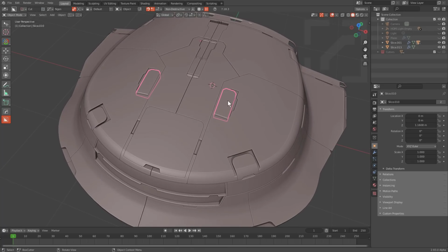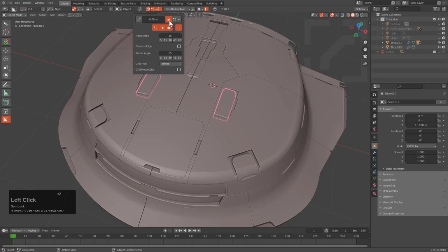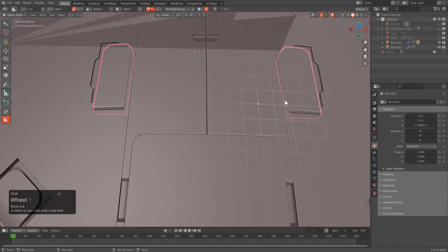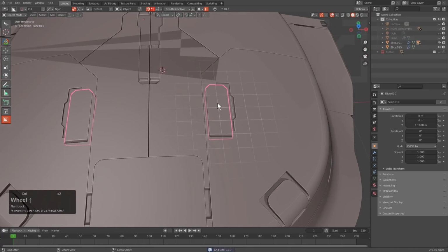Traditionally in Boxcutter, we had a grid where whenever you hold control, you're able to roll the wheel to make the grid larger and smaller on the fly as needed. However, when it came to extending its functionality, we also added a few additional options to make people's lives easier. For example, right now, in order to keep this grid up, I have to hold control, and the moment I release control, the grid is gone. However, I could activate this lock icon where if I tap control, the grid will remain up on screen, allowing me to work without having to hold down control.